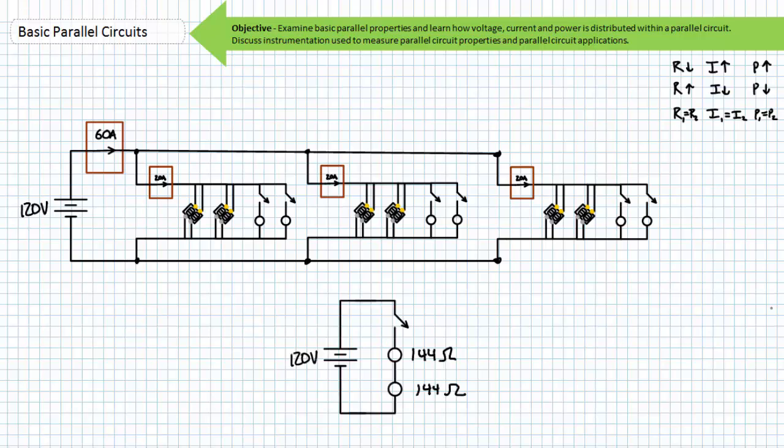Two identical light bulbs in series with each other would not experience a 120 volt drop as required, but rather 60 volts, as dictated by the voltage divider rule or any implementation of series properties and Ohm's law. These bulbs might be unusually dim, if they worked at all. If the filament of one light bulb in a series relationship opened, current through that light bulb would cease, as would current through everything in series with it.